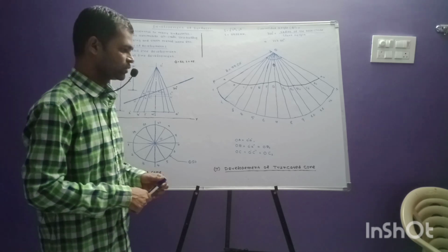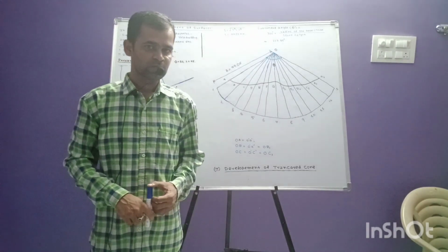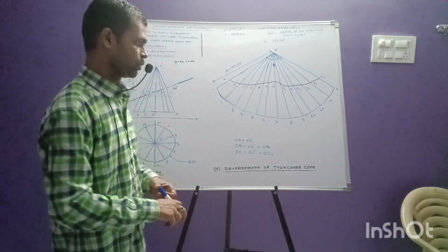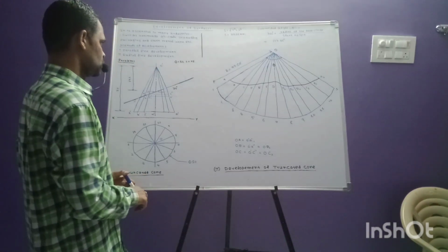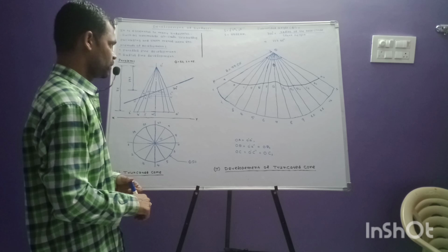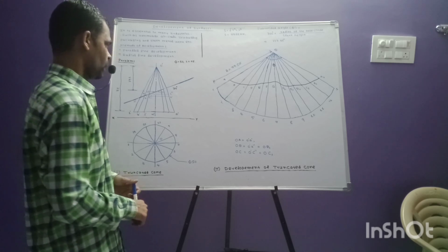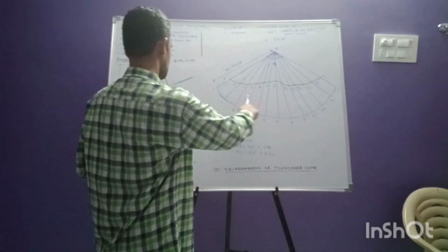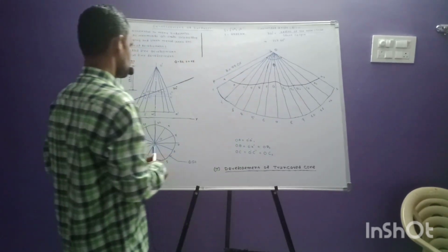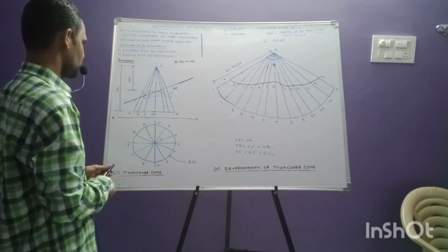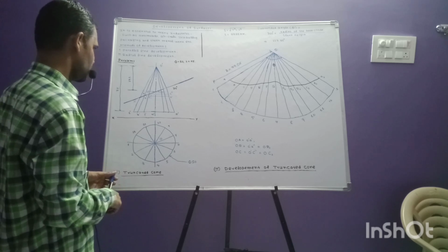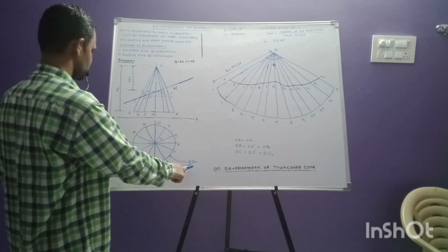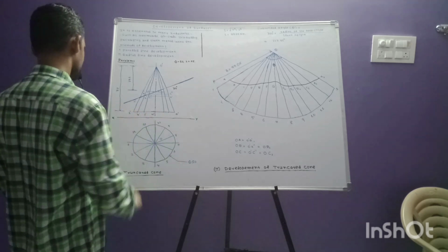So there is a simple difference between these two methods. So for regular solids, it is developed. In the radial line development method, it is developed like these surfaces. So we'll see one problem, which is a truncated cone, whose diameter is 50 mm and height is 75 mm.